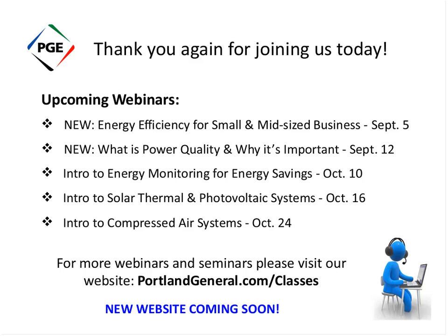So, should I go ahead and read these questions? Okay. So the first question is, how are color temperature and CRI related? They're somewhat related, but they're actually two different metrics. Color temperature has to do with the relative warmness or coolness of the light source itself, whereas CRI has to do with the accuracy of how well a light source renders colors on an object that you're looking at.